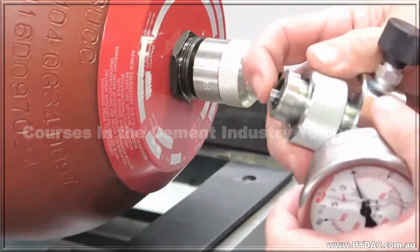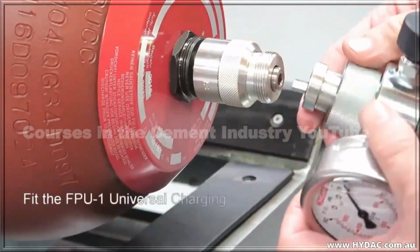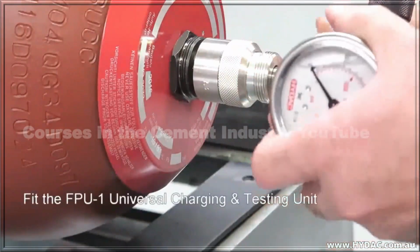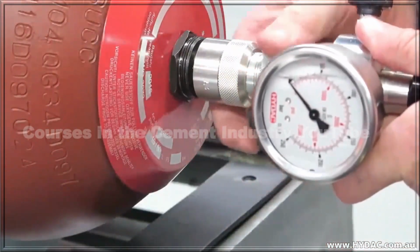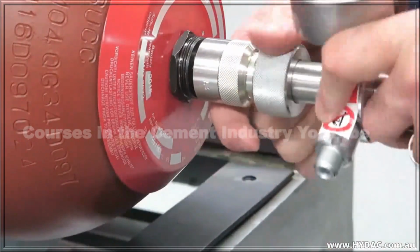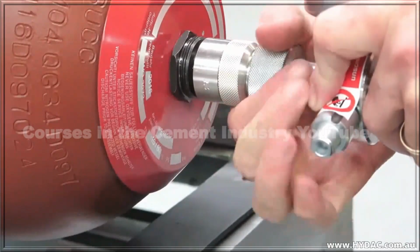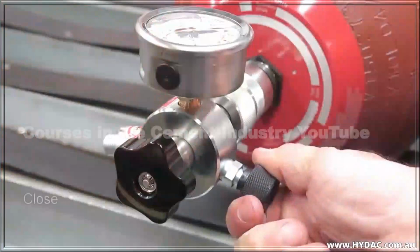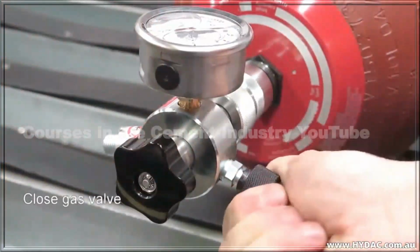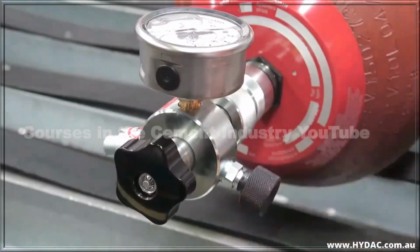Before fitting the Universal Charging and Testing Unit to the A3 adapter, first ensure that the surfaces are clean and that the sealing O-ring has been correctly fitted. Align the spring-loaded hex drive to the screw and screw the universal charge head to the A3 adapter, hand tight. Ensure that the gas release valve on the side of the charge head has been closed firmly. It closes clockwise, like a tap.